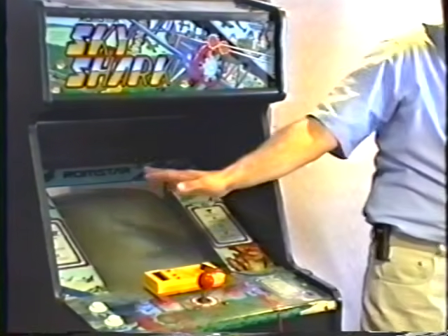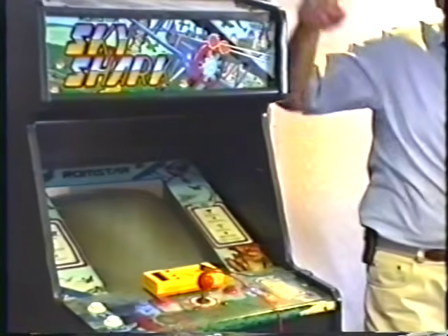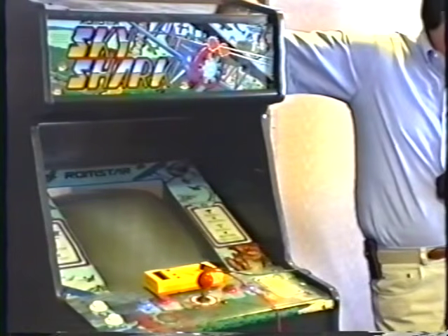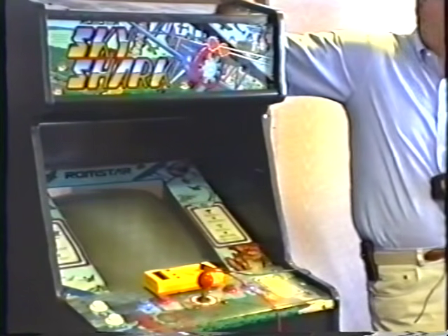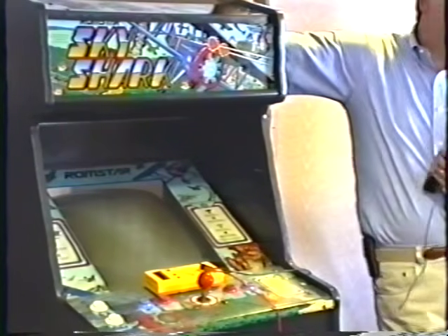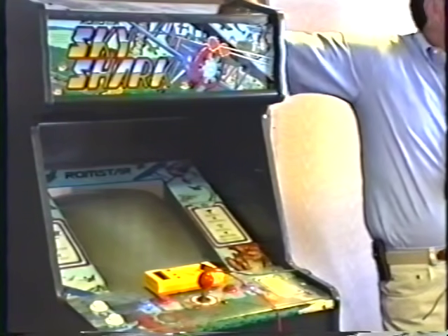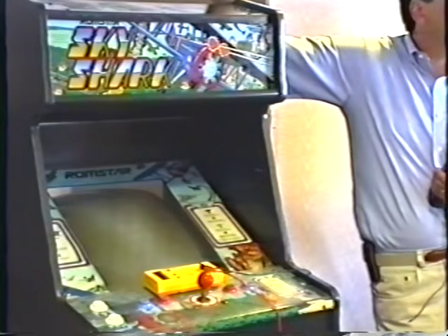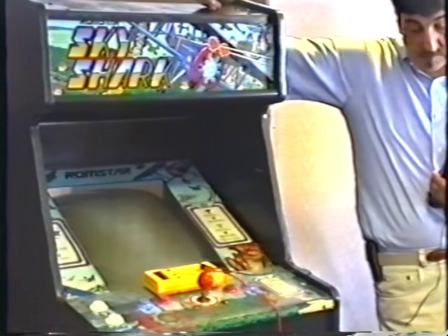If you have a blank screen, but you hear all the game sounds, you have a monitor problem, don't you? I mean, right away, now you know you have a monitor problem. You don't mess around with anything else. You don't poke on the logic board. You don't have to even check the 5 volts. You don't have to do any of that. You just go ahead and fix the monitor.